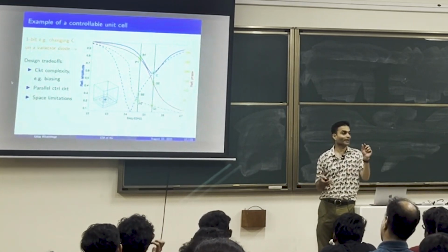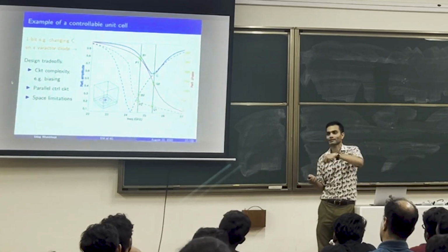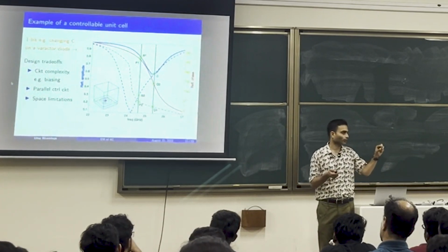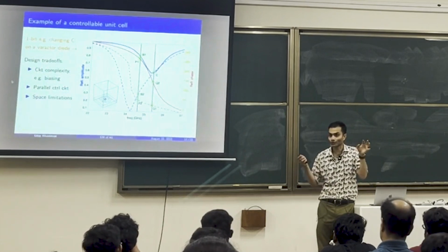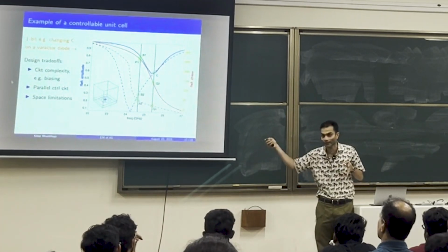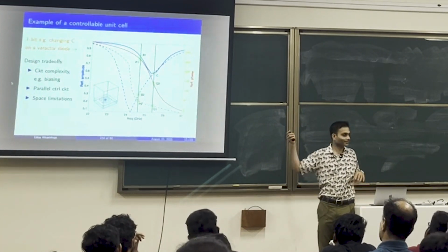What is the size of a capacitor? Right? All of these diodes, they need a capacitor, they need various things. Right? Now I need to start hunting for pieces of lumped elements which are like 1 millimeter, 2 millimeter in size. So it's going to get more and more difficult. If I start increasing from 10 gigahertz, if I go to 30 gigahertz, good luck, right? So this is why it's challenging.